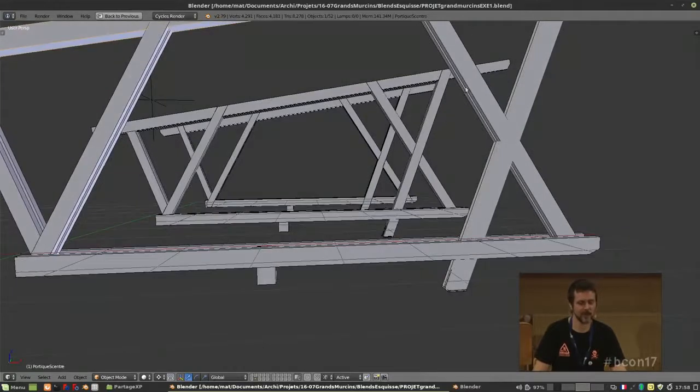And here, for example, in this part, there is a law in France that says that if a part is under 2.20 m, you have to make a sign on the wall or on the floor, so that people won't bump their head. So with the first design, I had the inclined part that was too low, so it would have been needed to make a smaller step here.